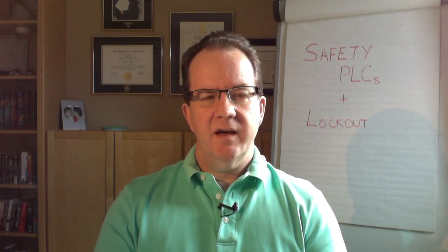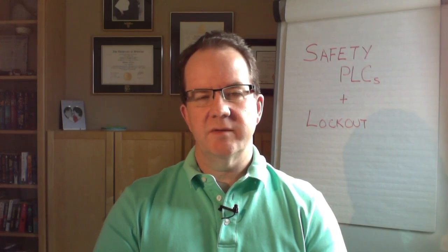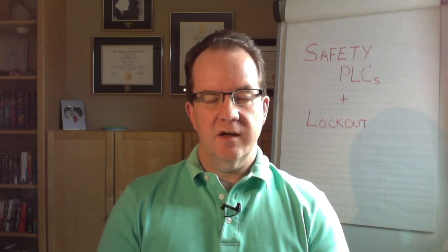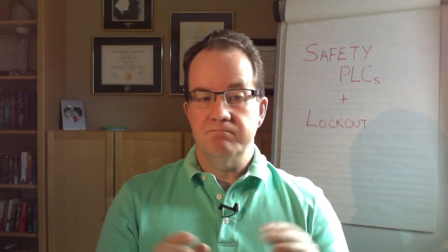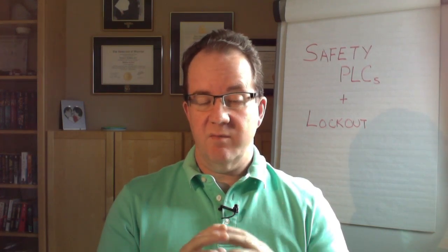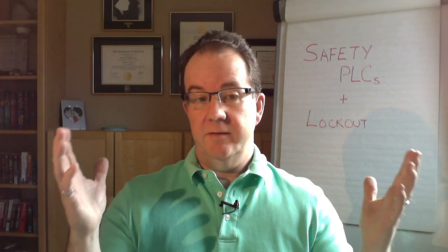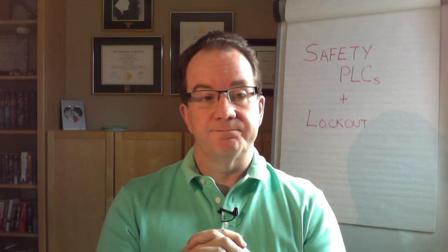So I think really in wrapping up, I need to say that for short time, simple maintenance tasks, minimal tools, minimal skills, minimal disassembly of the equipment, you can probably do those just using a guard interlock. You know, somebody needs to replace a busted drill bit or go in and squirt a little bit of oil on something, sure, that's probably fine. But if you're going to do anything that's going to take more than a few minutes, or where you're disassembling the machine, then you need to go to your full lockout procedure. Okay.